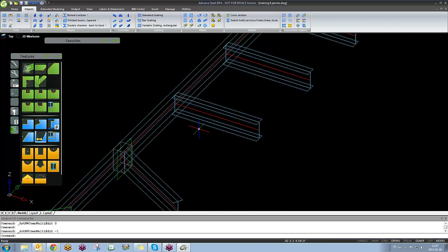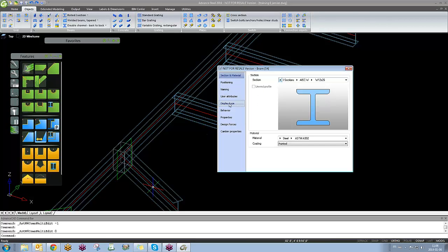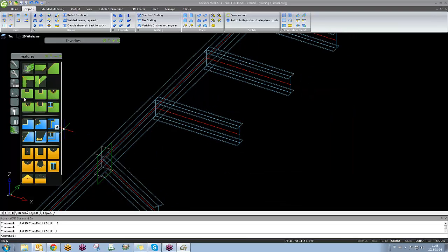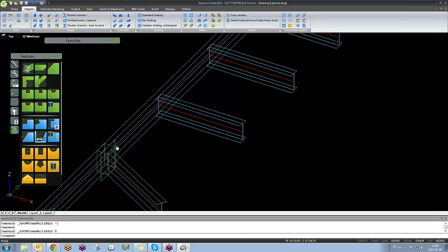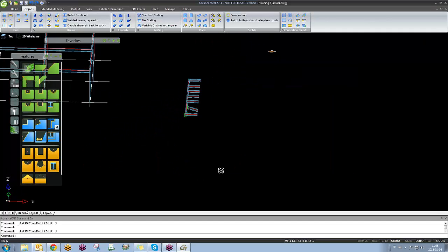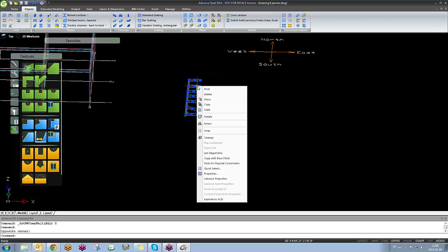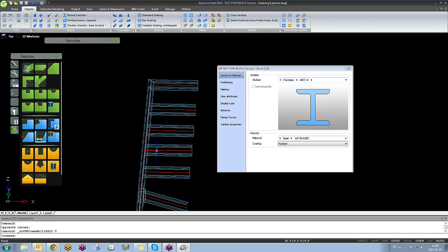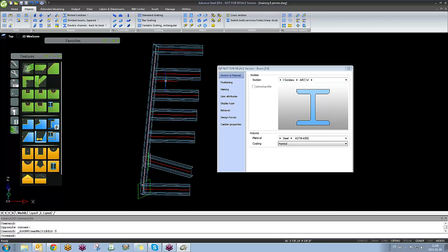Okay, but in order to get that feature on there, you have to go to... Yeah, so you have to double click on the beam, go to display types, make it features. Okay. So now will that show the feature on every joint that you have? Nope. Just on that one particular you're working on? Because I have double clicked on this one. For example, if I have selected all those and make it features, they will show the features on all the beams that I have here. Okay.